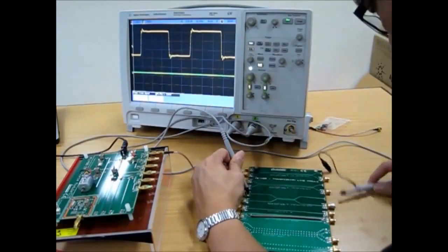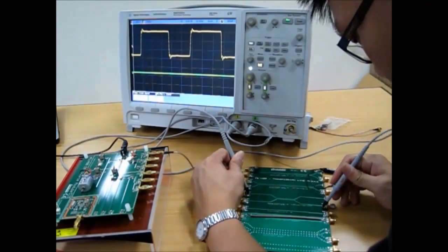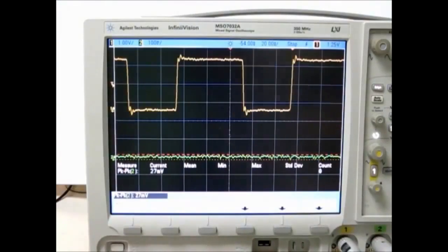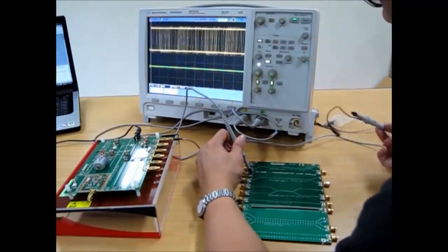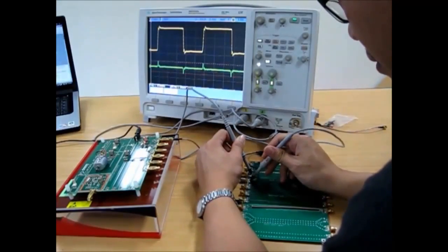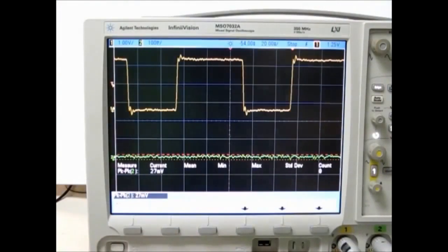Again, we are examining far crosstalk on this 50 mm copper line for comparing with the 100 mm copper line. The same phenomenon is also observed on the far crosstalk, which is a much smaller spot level compared to the longer 100 mm copper line. From these lab exercises, we can conclude that the spacing and the copper length of two adjacent lines can affect the crosstalk level significantly. So to avoid getting crosstalk interference from adjacent lines that carry high-speed pulses, you need to keep adjacent lines away from the high-speed lines at a sufficient distance.